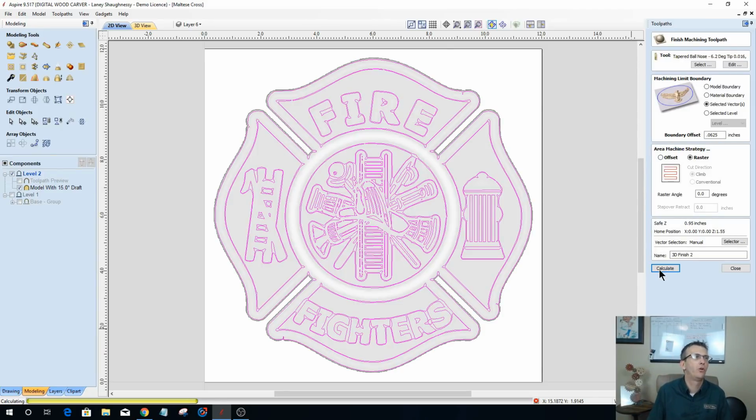If you remember to hold your control key down when you're creating that model from your toolpath preview, and then you trace it, turn off your original model and have the preview visible, trace it, and then that'll create the vector lines to do rest machining. I didn't want to get into that, but I figured, hey, why not? And because this is using a 32nd inch bit, it's going to take a second to calculate, as you can see. But I don't need to necessarily fill in things with dead space. But let's see here.